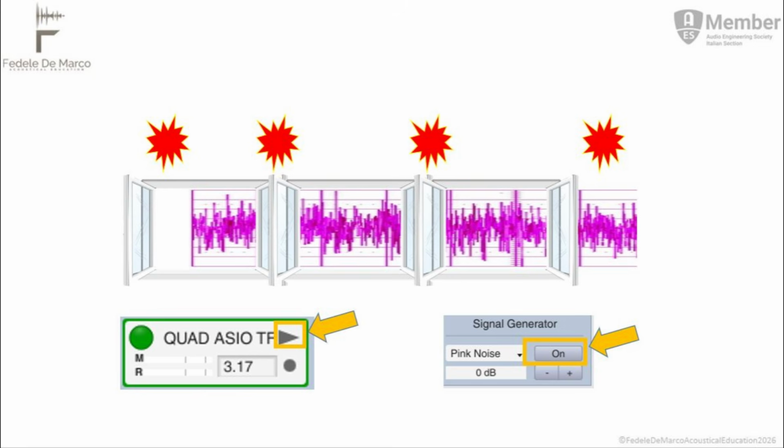These occur because of the lack of synchronization between the test signal and the measurement, especially during cyclical window transitions centered on the direct sound. This creates uncorrelated noise that is reversed inside the measurement, significantly lowering the SN ratio. Data windows help, but not too much.